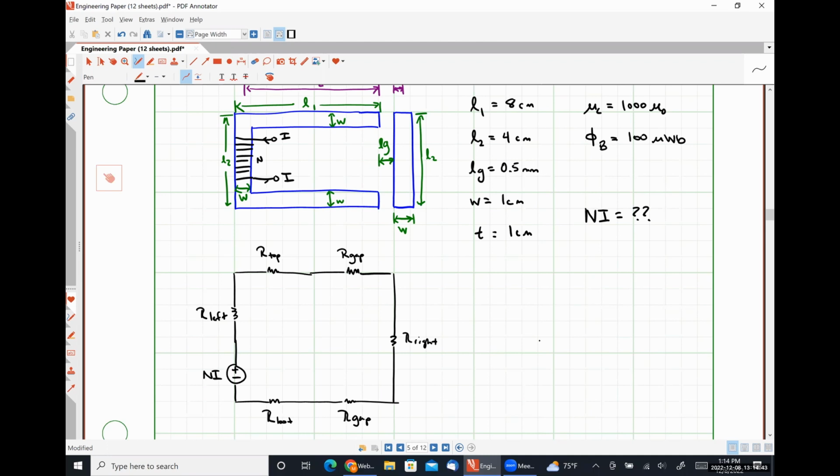That heat is going to generate some core losses. We can also have losses because we lose flux into the air in a gap, but we are not quite there yet. So you're 100% right that in a real system, it's not going to behave perfectly like this, but let's figure out how the ideal things work before we start breaking everything.